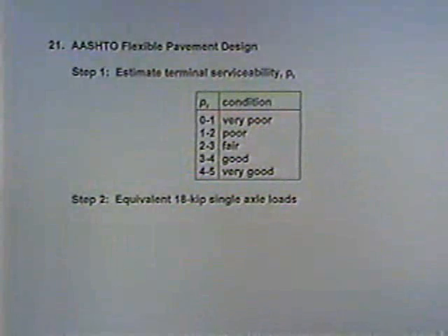So when we look at that, we estimate what our terminal serviceability index is going to be before our first resurfacing. And there are some charts that you'll see in a few minutes in your notes. You need to read the labels very closely because some of them are for a serviceability index of 2.0, others are for a serviceability index of 2.5. Step 2 in the procedure, we are going to come up with the equivalent 18 kip single axle loads using one of the procedures that we just went over, and there's a couple of them that you can work with.